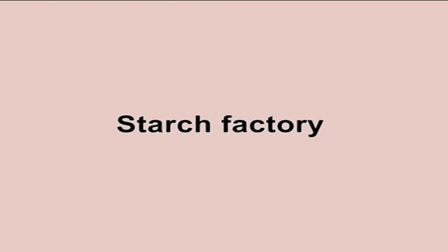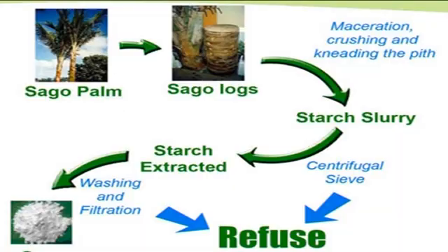So, treatment methods employed in different industries is the last topic of today's session. One important industry is the starch factory, where the wastewater from starch factories has a high organic load and usually consists of easily degradable matter. The undissolved organic contents are mainly carbohydrates and proteins. The fat content is normally 10%. Usually, this kind of wastewater does not contain any toxic substances.